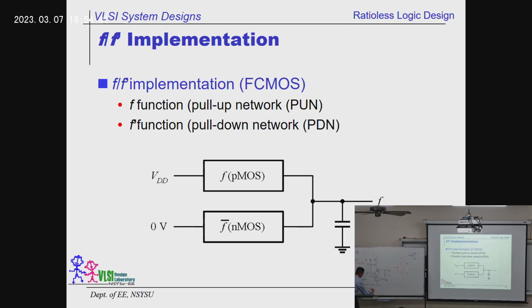Nothing happens, because if we turn on one of the transistors with one single input, the effect is the same. So if we see parallel, you don't have to do anything. I guarantee you that the size for these two transistors will be the same as the one in the pull down block of the inverter. So it's guaranteed to be W.